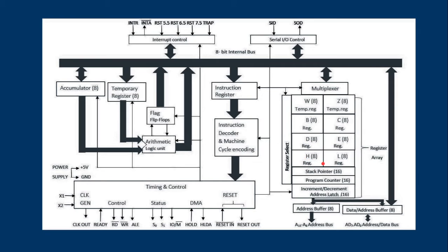Likewise H and L also. The stack pointer is a special register which helps to contain the data in stack mode. That is, we can use the data which is needed for some recursion technique or some other expression, postfix evaluation. We have seen so many applications of these stacks, and these stacks have a pointer to indicate the top of the stack, which is the stack pointer. The program counter is the register where all the instructions are first stored, then executed. So whichever instruction the program counter points to is taken and executed by the instruction decoder.